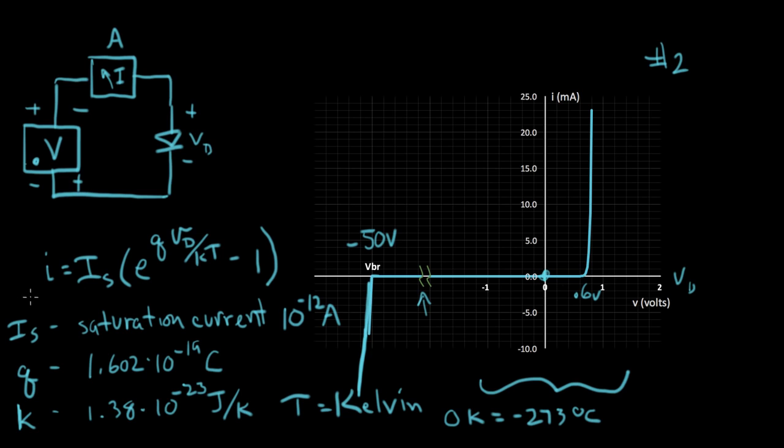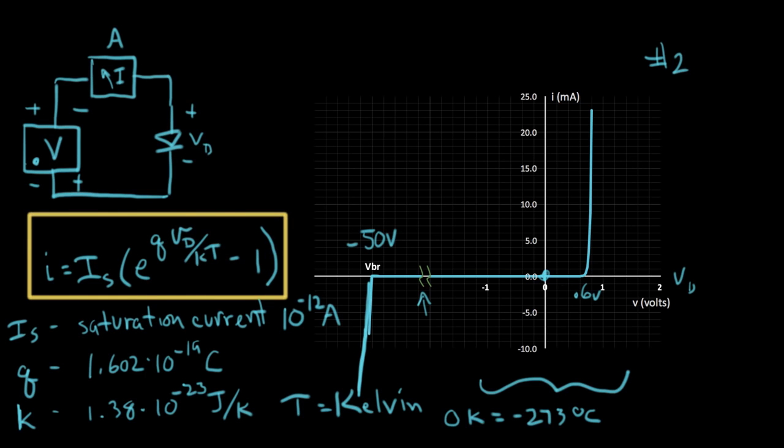So this right here is the diode equation. That's the diode IV equation. And it has its exponential term in it. But when we look over here, maybe this doesn't look like an exponential curve. You haven't seen a curve like that. But that actually is just a trick of the scale of this drawing. So what I want to do now is I'm going to zoom in really super close right on this origin right here. And we're going to see how this exponential term shows up. And we'll see what the meaning of IS is.